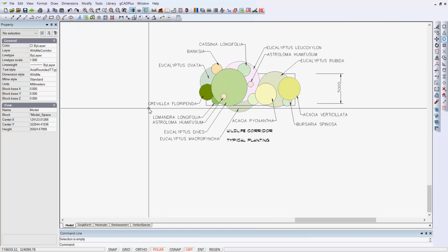So it's by no means a detailed discussion of wetland design, but you really want water draining through the site to the lowest possible point and then moving through a series of zones where, ultimately, in the final zone, you want to use the plants at the edge of the shoreline and other algae to clean up the water that's coming in.